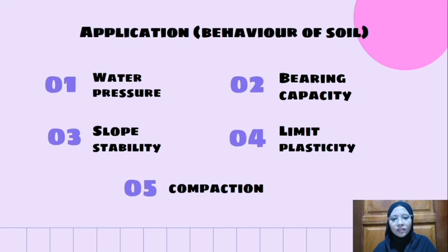When organic matter is added to soil, the plastic limit increases without affecting the liquid limit significantly. As a result, organically enriched soil has a low plasticity index. Lastly, the soil compaction test is the test that can determine soil sustained mechanical stress. When stress exists, void volume will decrease and will cause densification.